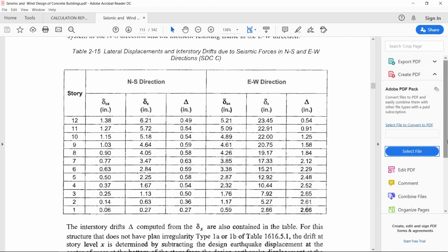I will check for steel structures; what I felt is that in steel STAAD is good, but in concrete, no, there are so many limitations. Better not to use STAAD for concrete structures, look for something else. Maybe in my future lectures I will try to use SAP or ETABS on the same problem, and check whether they are giving the correct values or not. Hopefully you will be satisfied, or you will agree with me.